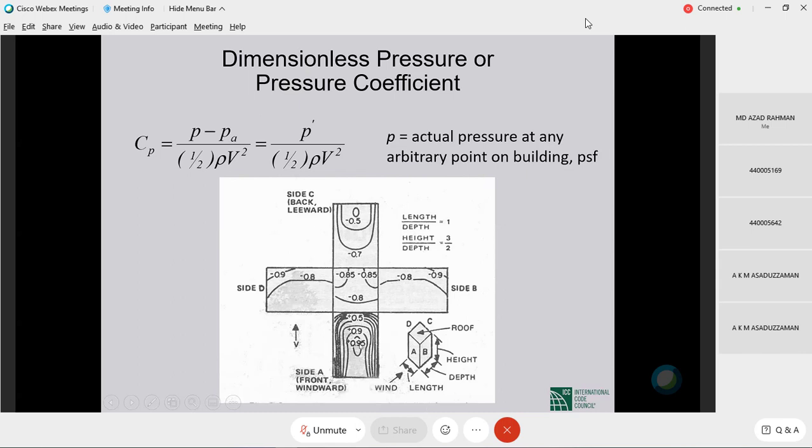You see that at the stagnation point, and what is being plotted is pressure above ambient, or pressure divided by the stagnation pressure, 1/2 rho v squared. So at the stagnation point, we have 1.00. But as we move away from the stagnation point, you see the numbers go down. However, over the entire windward face, the numbers are positive. But on the roof, the numbers are negative. On the leeward face, the numbers are negative. On the side faces, the numbers are negative, and so forth. Okay. So this is the actual pressure distribution.